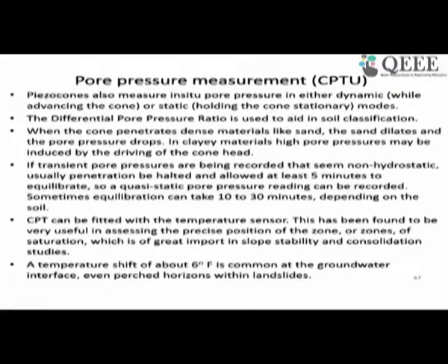So the transient pore pressure also can be recorded from this piezo cone or CPTU, whatever you call it, the cone penetration test with piezometer option. In the transient case, you need to wait for 5 to 10 minutes to settle the pore pressure, or sometimes you may have to wait 10 to 30 minutes, depending on the soil, how much time it takes to dissipate the pore water pressure.